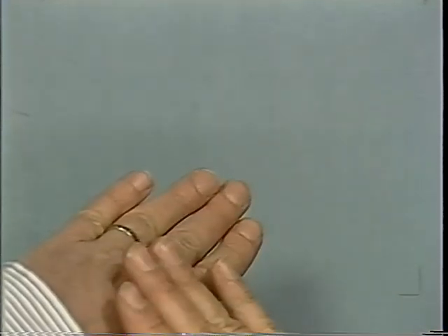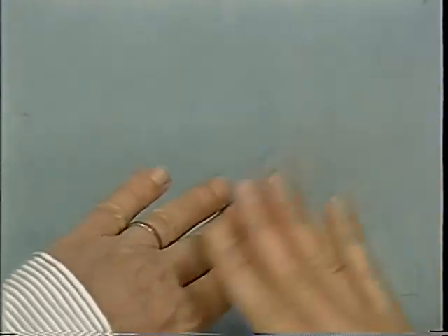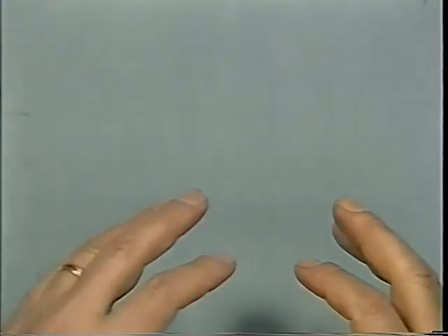And then as soon as the free surface of that liquid or this cross-linking material became ribbly, he said that's the instant of gelation. Somehow the molecular clusters became big in that system, and flow changes due to that. And that's probably a reasonable way of detecting the gel point.